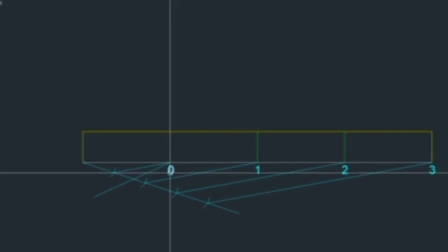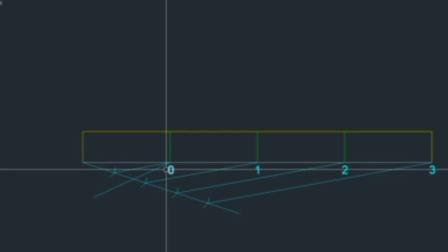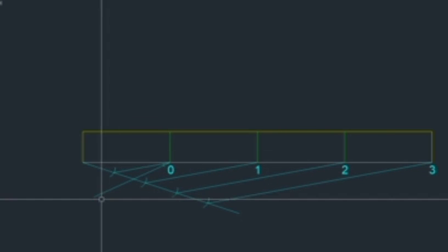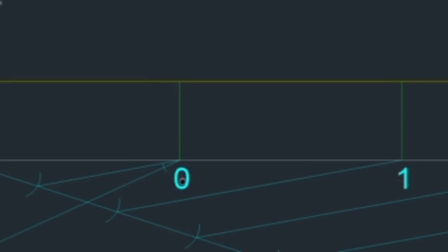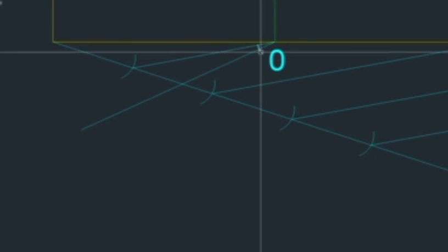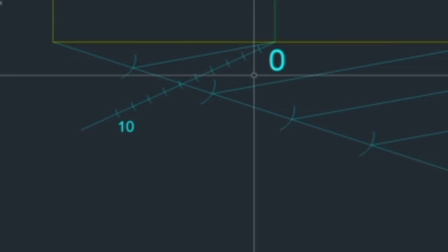So then what I have to do? You take any radius in your bow compass, you cut one arc. Similarly, you can make 10 arcs here. So I have taken this much length. You understand here? From here to here I cut. So this length parallelly, put a leg here and cut. Put a leg here and cut. So similarly, 10 arcs you have to mark.